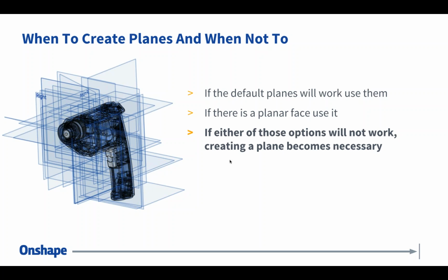And that's probably one of the first questions that I would ask the user. Do you have a standard plane, a front, top, or right, that will do what you're trying to do? Create a sketch on that plane. And that's one of the first things I'll ask a new user. If you have a default plane that will work, use it.